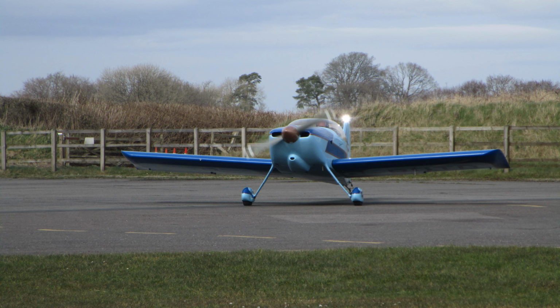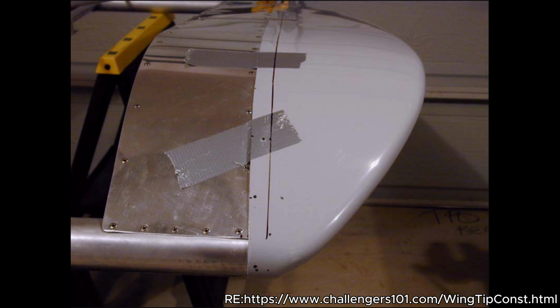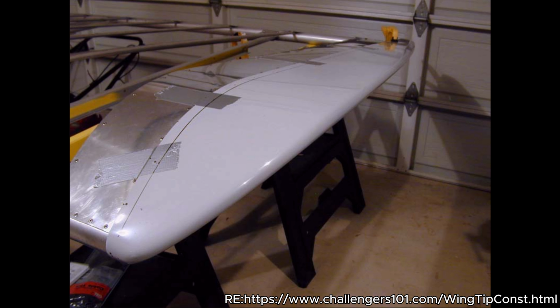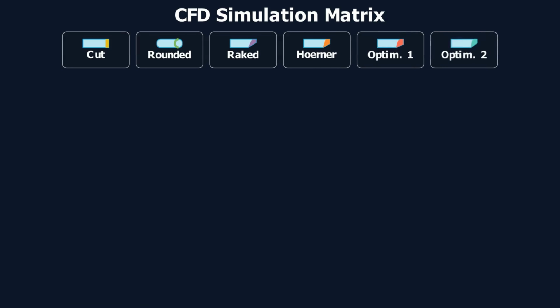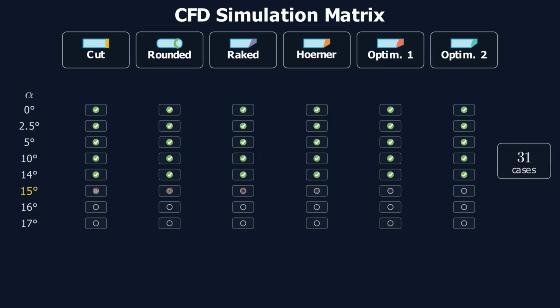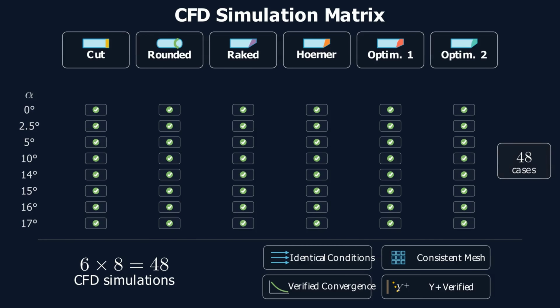This improvement aims to quantitatively evaluate the separation threshold of leading edge bluntness on Hoerner wingtip aerodynamic efficiency by constructing the edge morphology closest to ideal theory, thereby identifying the root cause of why previous simulation data did not meet expectations. Finally, these two optimization models were added to the calculation matrix to compare the results of all 6 models.